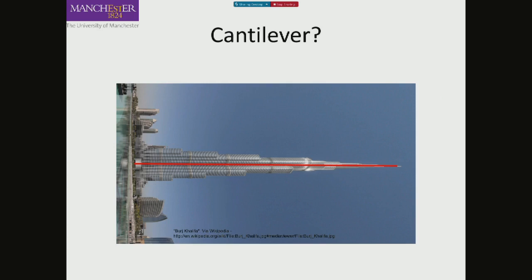Again, say Burj Khalifa, for example, you can consider it a cantilever structure, and due to wind loading, which would probably vary in a triangular fashion from the ground to the top, that would create bending on the structure. Now, consider the thickness or width of the structure near the base as opposed to the top.